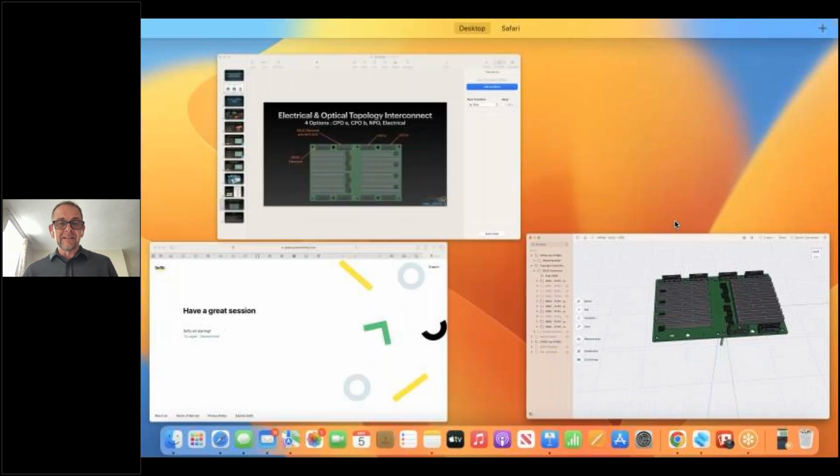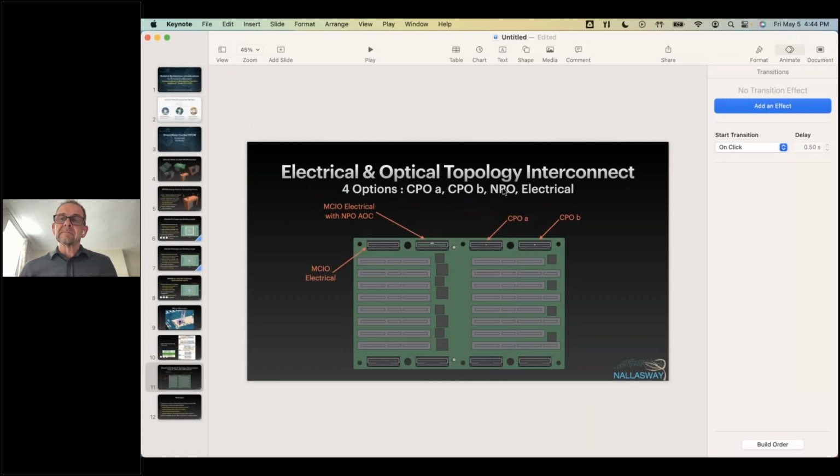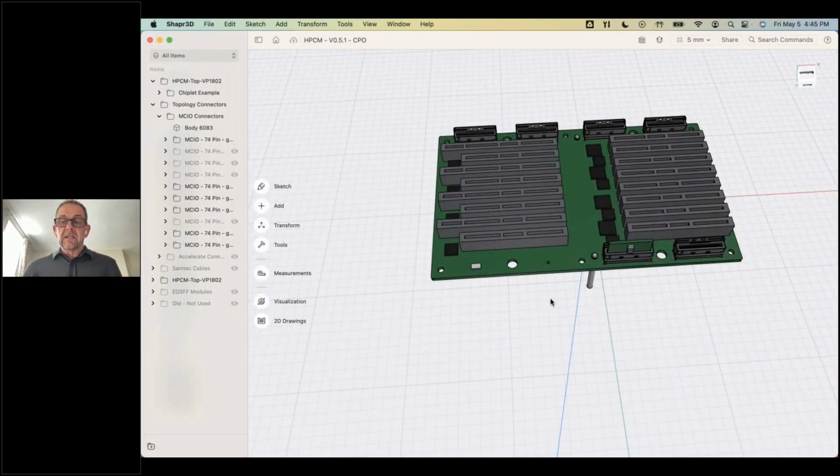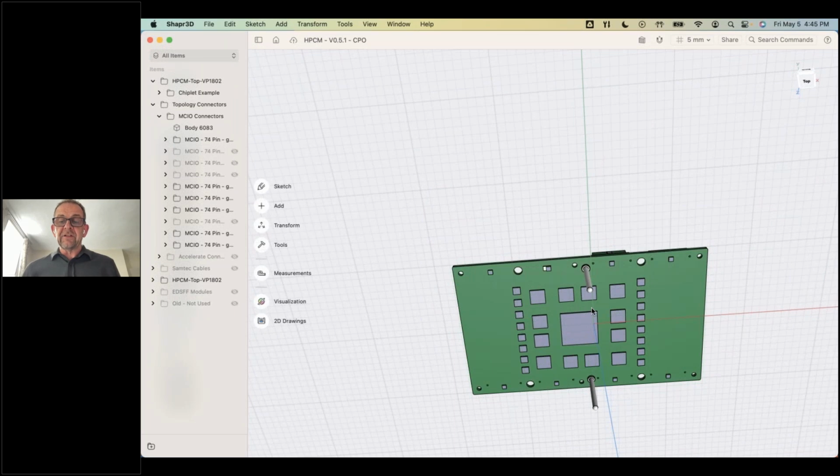Okay. Maybe another question, not about the optics, but just from my understanding, you're talking about these rectangular black connectors. Those would deliver power and data, or power or data, if you're staying in the electrical domain, like this MCIO. So the MCIO, it doesn't. The power to the module comes from these two pins here. These are the 48 volts in the module. It's a blind mate. When you plug the module into the wall, it provides 48 volts of power and provides the water or the coolant to cool the module.